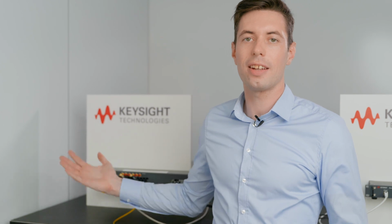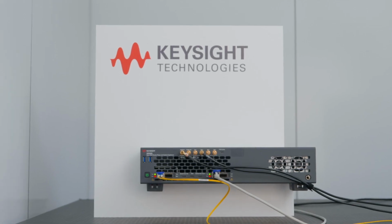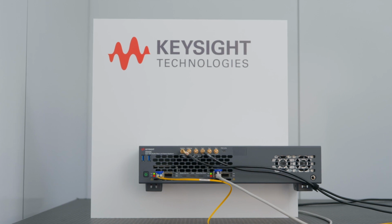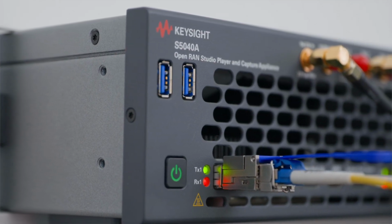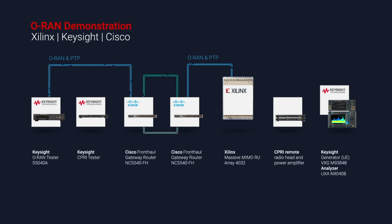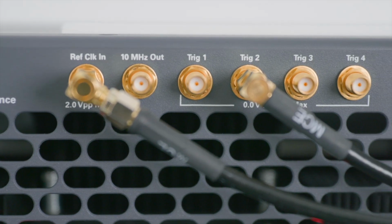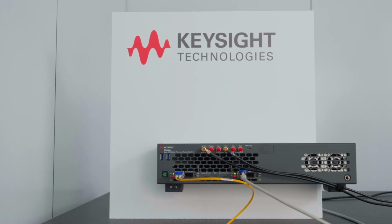First, we have the Keysight S5040A O-RAN tester. It's basically an ODU emulator with parametric control of the O-RAN interface. It emulates various features of the O-RAN standard and can mimic different O-RAN IoT profiles. On the S-plane, the O-RAN tester acts as a PTP grandmaster, providing synchronization to other equipment. In addition, it also provides triggers to measurement equipment to ensure that the device under test and the test environment are on the same clock and time reference.